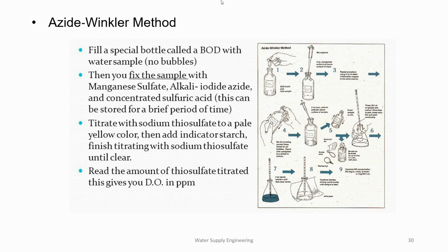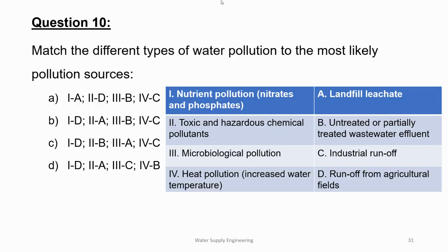So the terms and methods are same. Only thing is the compound that is used is particularly mentioned here as alkali iodide azide, manganese sulfate, and concentrated sulfuric acid. That's the azide Winkler method or modified Winkler method. All right. Moving on to the next question.